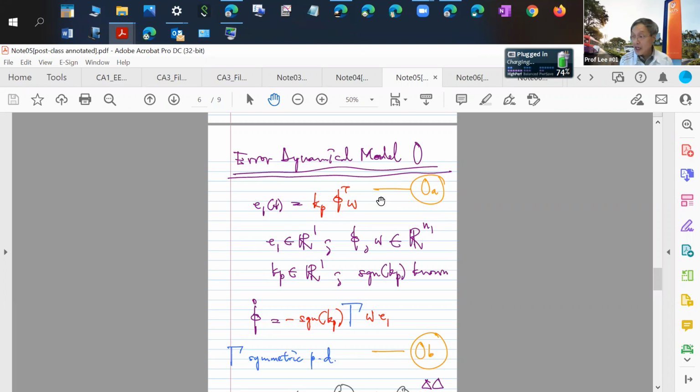And then, as a result of this adaptation, you are guaranteed that the tracking error is going to zero. So your three signals are still running all over the place, but staying in a two-dimension plane. Then all that will happen is that the parameter error will adapt, but it has to obey the fact that E1 tends to zero. It will adapt and basically rotate until it becomes a normal vector to the plane in which your signals live.